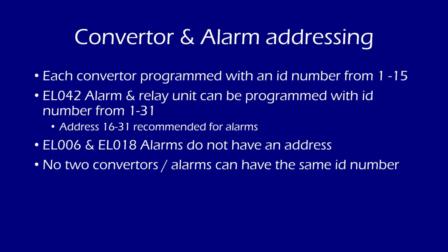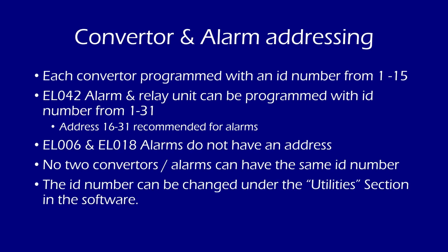No two units, be it an alarm or a converter, can have the same ID number. Every converter or alarm should have a unique ID. The ID address of the converter or alarm can be changed by going into the environment software under the utilities section.